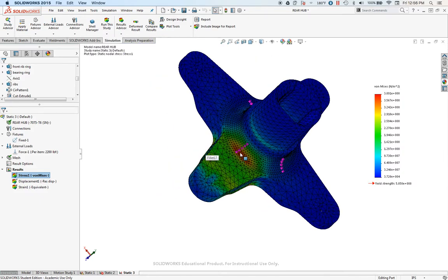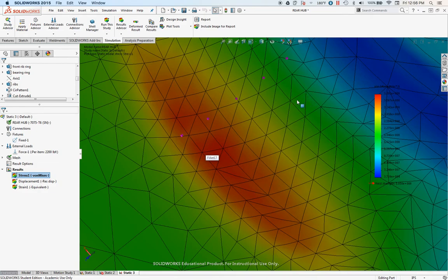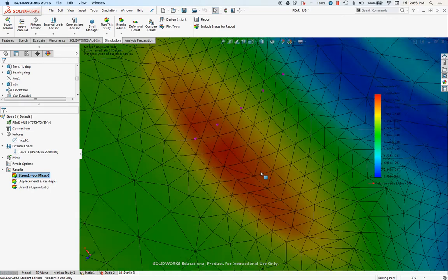Alright, so now let's look at this stress point. And you can see the gradients are looking a lot better. So right up here, we had a whole element going here, here, here. And now we have more packed in there. So this is all green, all green, all green. And this one, the gradient's a little bit, I would say, it's probably okay because it's not your highest stress region. Especially if you were close to failure at this point, I would refine it quite a bit.